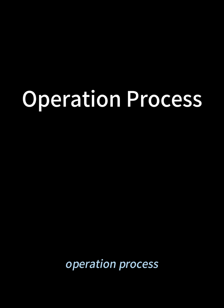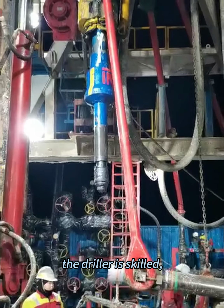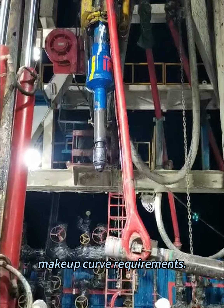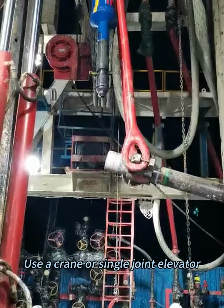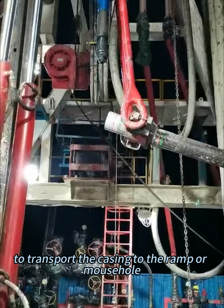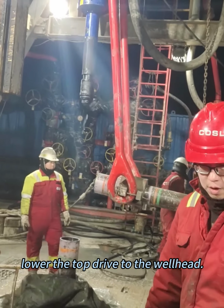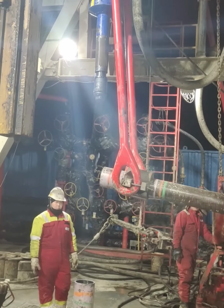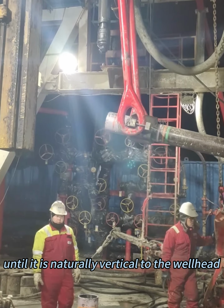Operation process. When the wellhead is relatively aligned, the driller is skilled, or for standard casings without strict makeup curve requirements, the CRTi can be used for makeup. Use a crane or single-joint elevator to transport the casing to the ramp or mouse hole. Lower the top drive to the wellhead, where the elevator can grip the casing on the ramp or in the mouse hole. Raise the top drive to lift the pipe string until it is naturally vertical to the wellhead.